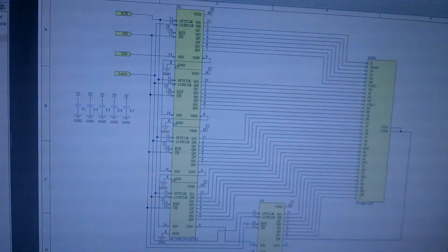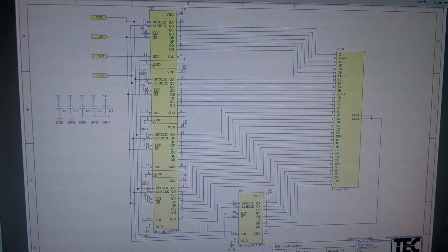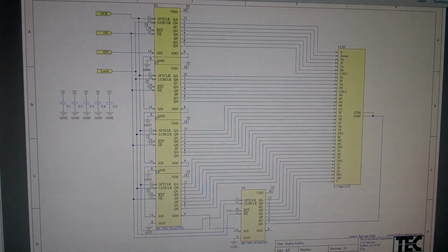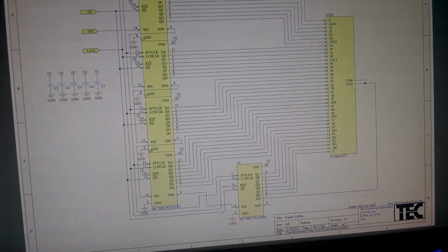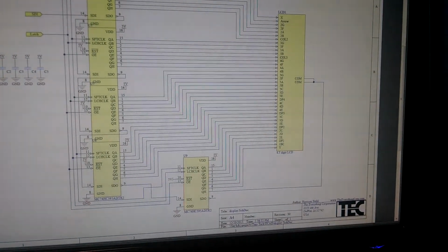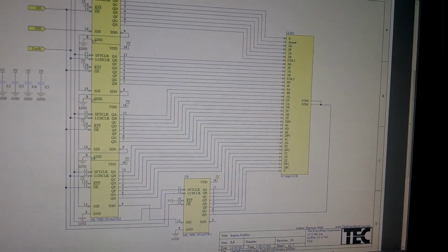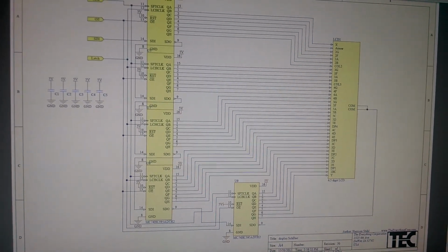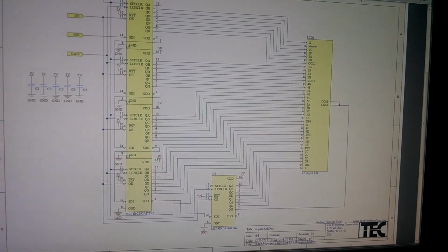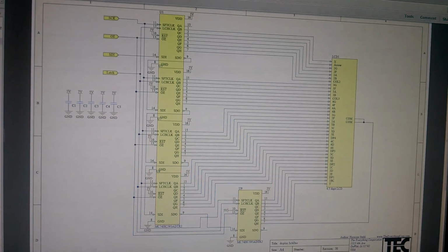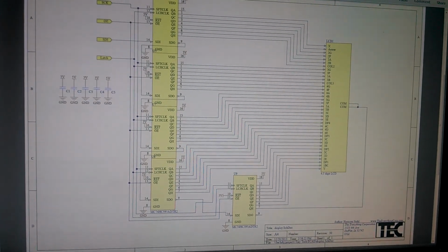Here's the schematic. I'll throw this up on the GitHub too, since it'll be the same as the demo script. This one actually has 2 separate backplanes, but I tied them together. I haven't used LCDs before, so I don't know; that's what you're not supposed to do, but it works either way. And really this Shift LCD library only works with single backplane displays, so usually anything over 5 or 6 digits is going to be a little bit tougher to use this with.